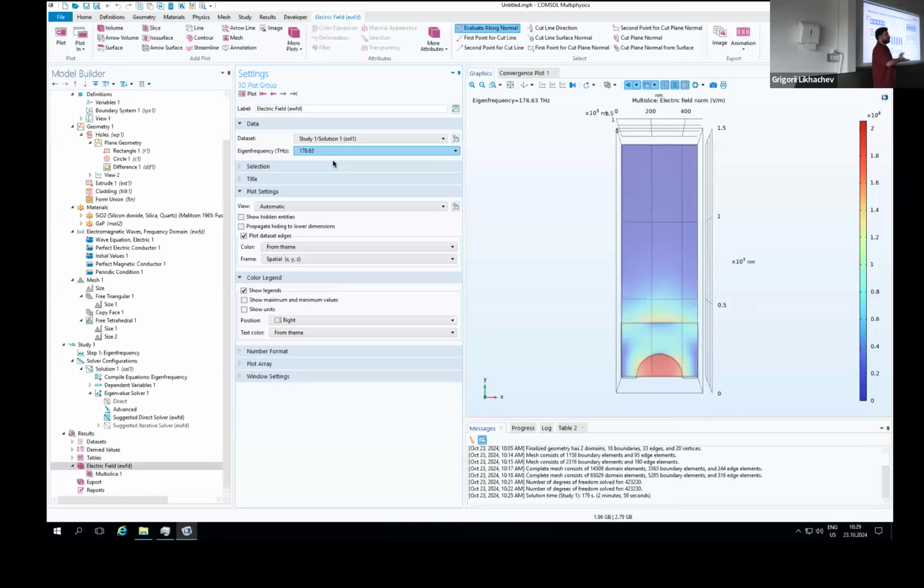If you have the fundamental mode, beautiful. In this case, you're not perturbing the center where you have the maximum of the electric field, but you're perturbing the edges. That means the effective refractive index of this region should be larger than this part here, where you have the hole in the middle. So your index contrast is not as large, and that's why you will have a bandgap that is smaller than in the case of the holes.